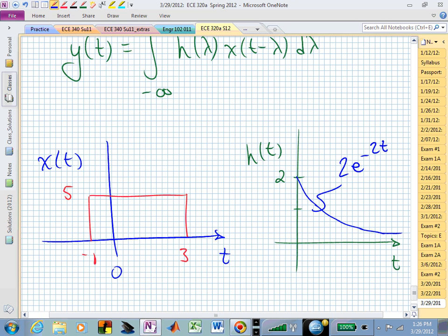And what did we say our time constant was? 1/2. So in 2.5 seconds, we basically are done with this system's response if we hit it with an impulse. Okay? So if we hit this system with an impulse, we would quit seeing a response after 2.5 seconds, right?